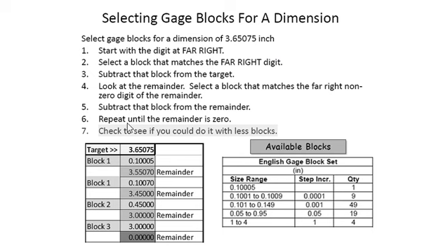One of the students, I remember, was asking how do you calibrate the gauge block, because the gauge block is a service standard. You can calibrate by measuring with another standard like micrometers or calipers or something, okay? Calibration is just making sure that they have the least contaminated surfaces, and that they have the exact specification that's mentioned inside of the gauge block box, right? So it's kind of like a check before you use it for measurements.